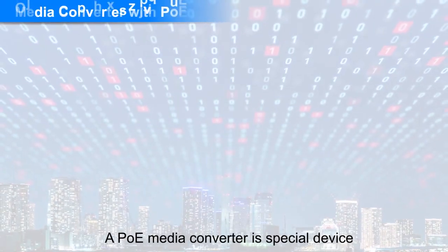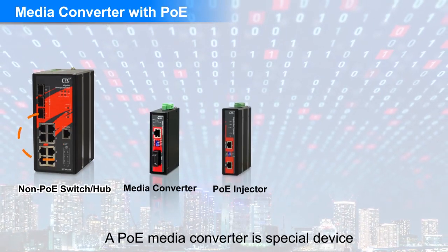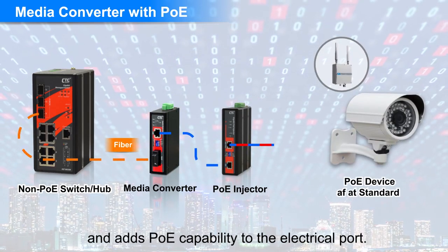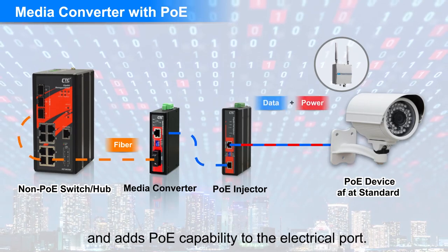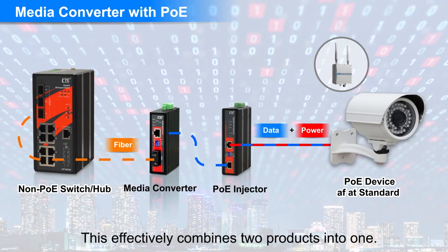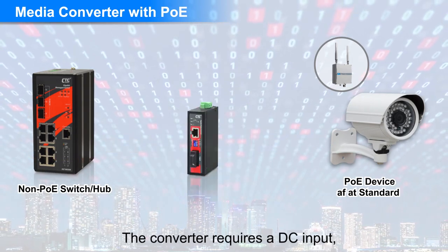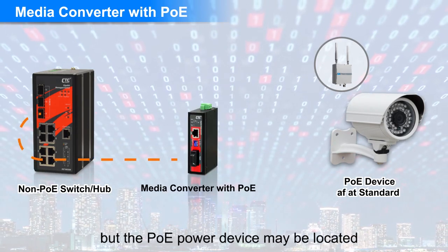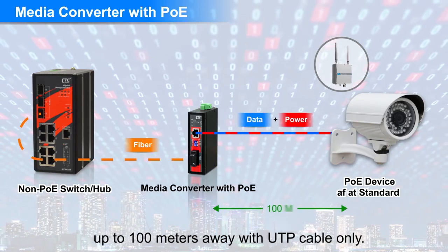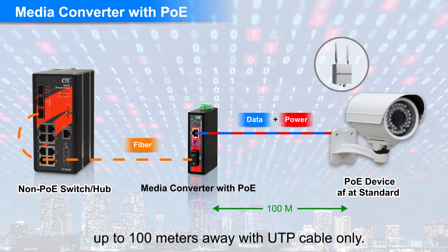A PoE media converter is a special device which combines an optical to electrical media converter and adds PoE capability to the electrical port. This effectively combines two products into one. The converter requires a DC input, but the PoE power device may be located up to 100 meters away with UTP cable only.